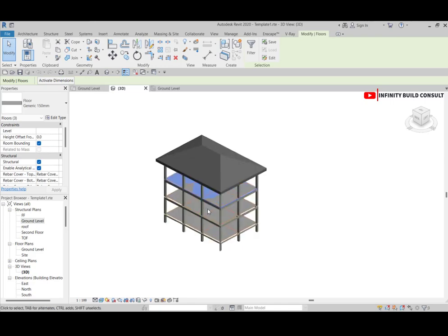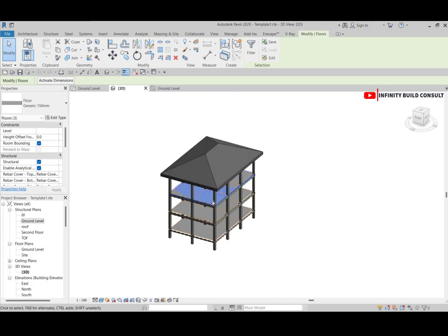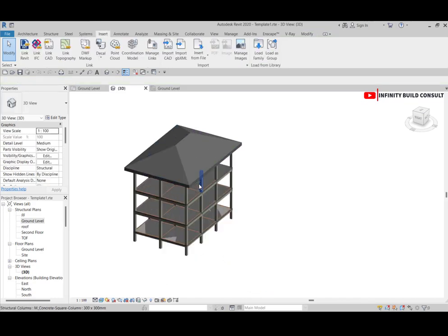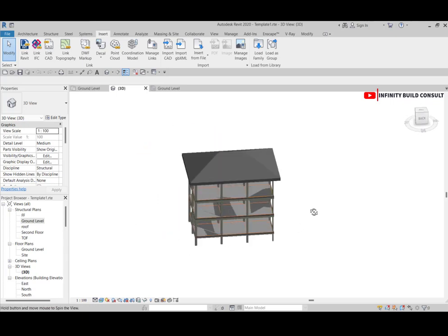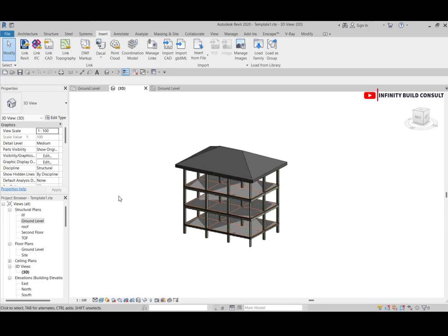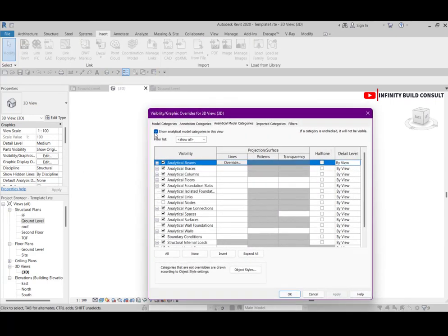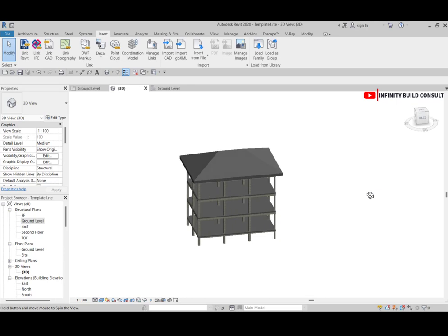Immediately it gives me the selected floors in my model. So that's how filter works. You are going to do one or two steps with the filter here, and you can know more about it. I think we have to remove our analytical elements so that we see how our model looks.